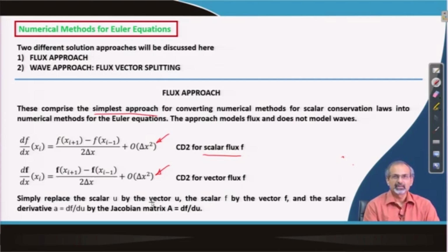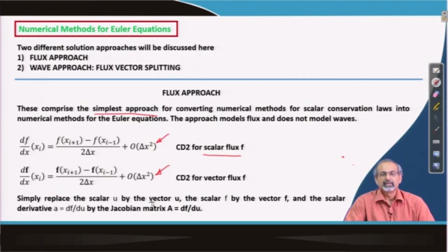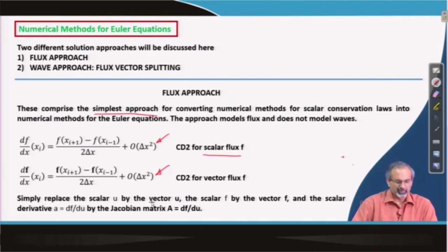If you try to do numerical integrations, which you need for say finite volume approaches, the rules also remain the same there. So, that means the regular rules which we have seen applicable for scalars are extendable to vectors in this manner, and that is the basis on which the different terms would be discretized in the vector model problem.